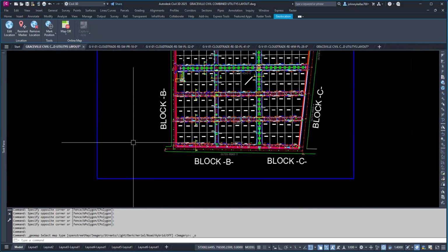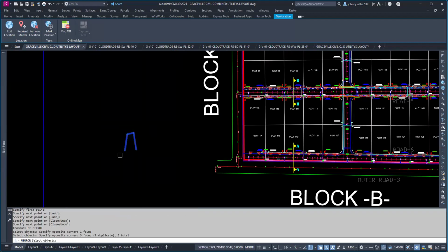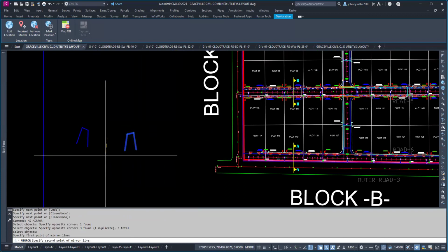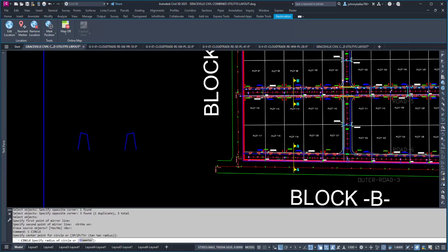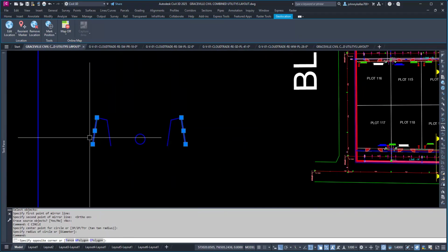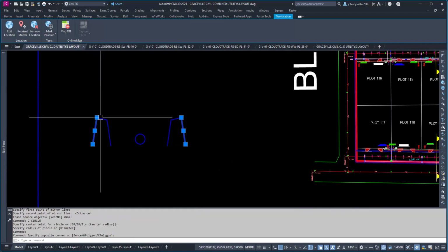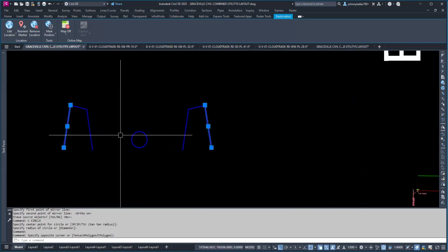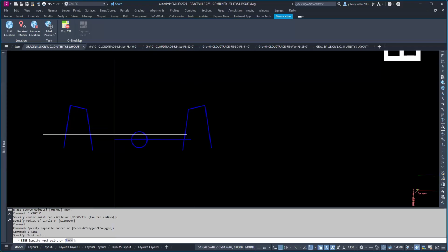Let me just draw for you as a sketch. Let's call this a section. For example, this is the edge of the road here, and this is the edge of the road. By the excavator, we will create a wall, a bound wall, okay? Then we will pump the sand in between. When we are pumping the sand here, for example, the sand reached to this place, we are going to raise up the pipe.